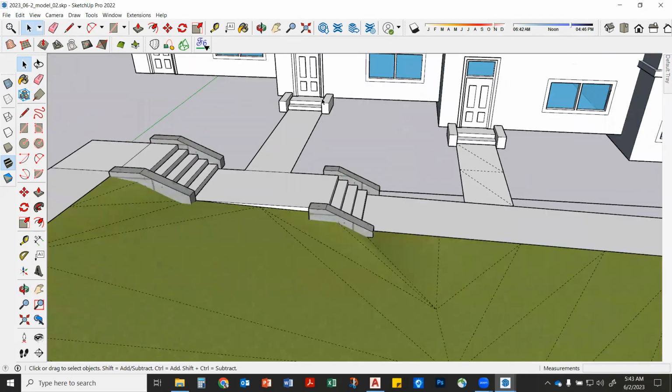And then we're going to make a tin in between these two walks. Tins, tins, tins, right? The neat thing is you're practicing this over and over again because this is like the basics of modeling topography in SketchUp: defining an area and then making a tin with it. Now, if you're importing, you can actually import topo as well, just like I showed you guys, and easily make a tin with your topo. Yeah. But even with that, it doesn't always come clean because of how it runs through walls. So you kind of have to know this and go back and forth with that process too.